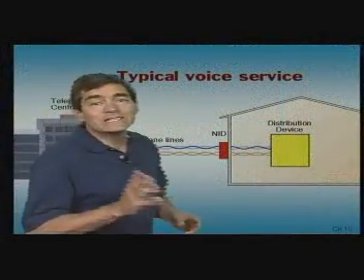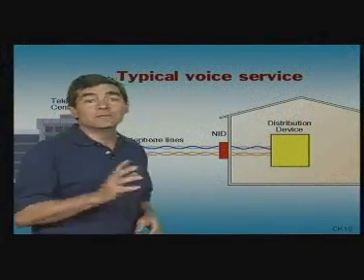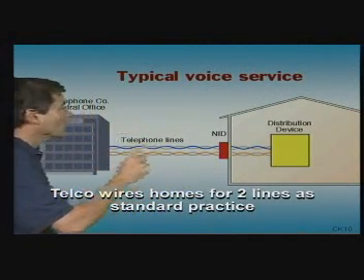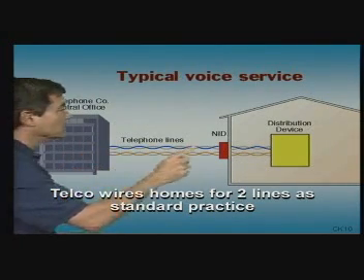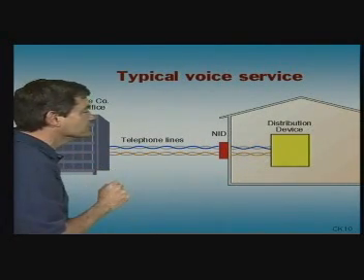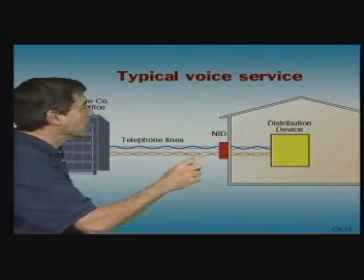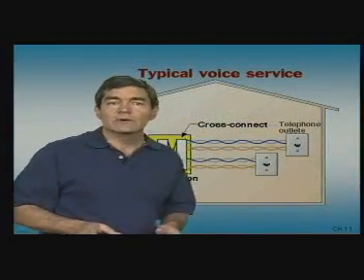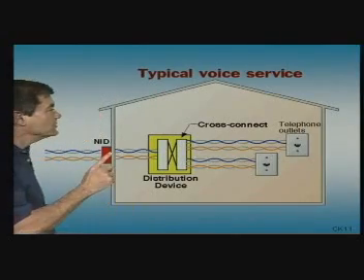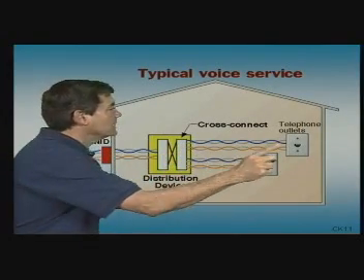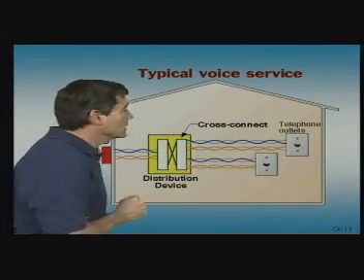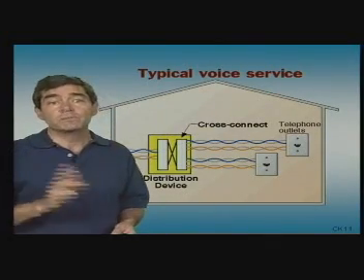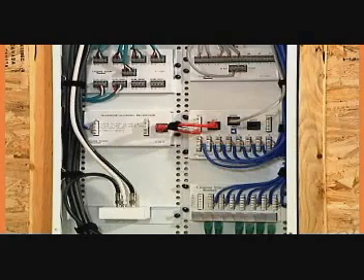The traditional voice network starts at the telephone company's central office. Each telephone line uses a pair of wires from the office to the network interface device at the house. A pair of wires for each line then runs to the structured media center. Now, the media center allows each incoming line to connect to multiple branch cables to individual telephone outlets. Each branch cable contains 4 pair of wires to support 4 voice lines.